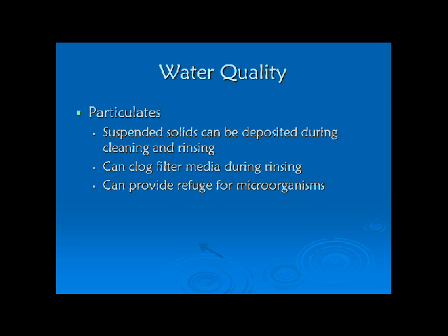The little bits of suspended solids can actually create shadows from this, and bacteria can find a little spot to find refuge inside that or around that particle, and actually will be shielded from the ultraviolet. So of course you're then thinking that you have clean water when actually it's getting contaminated downstream. So for that reason, there's often a particulate filter immediately before these ultraviolet filters, and so a very important step. So particulates, we can think, well, it's maybe not such a big deal, but really it does create some problems for us.